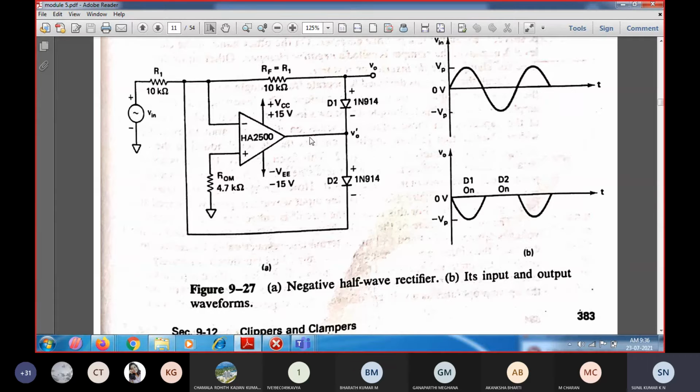So that means since we have given positive signals, we will be getting V naught dash. This positive will not get saturated because we have employed the negative feedback. Since we have employed negative feedback, the op amp will not get saturated in the positive direction, and hence the output will get settled at zero.